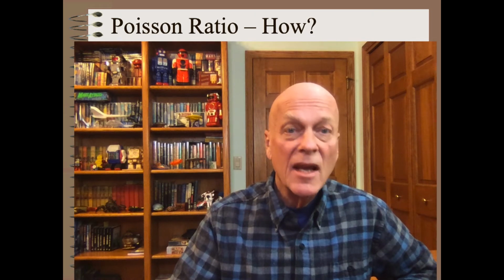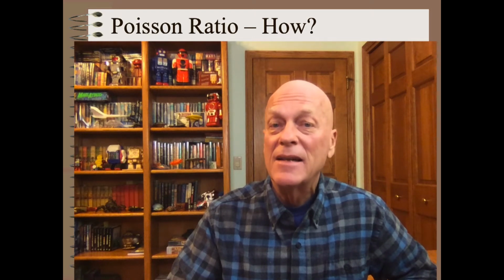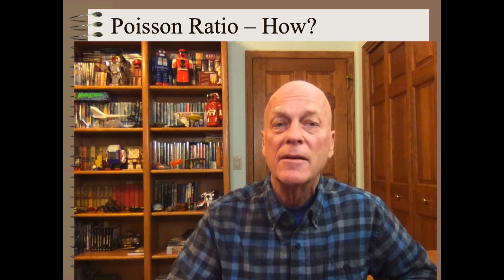So, how do we measure Poisson ratio? If we are lucky, because this is a difficult test to do, we could merely look it up on the internet. If the internet does not have a value for Poisson ratio for our product, we have to invent or contrive some tensile test fixture to measure it.